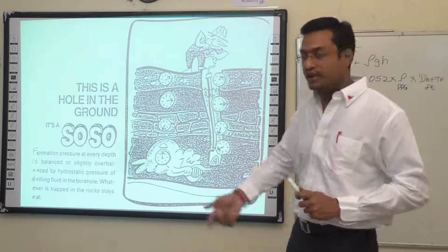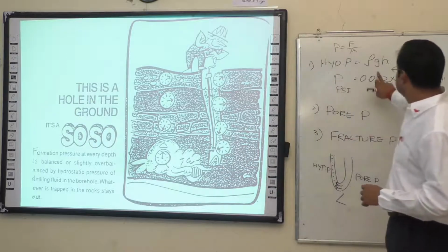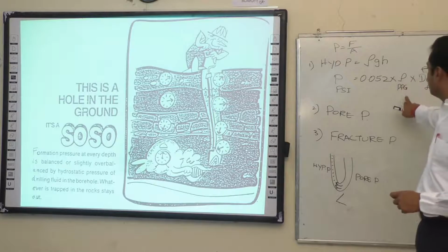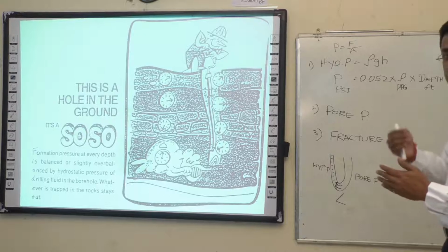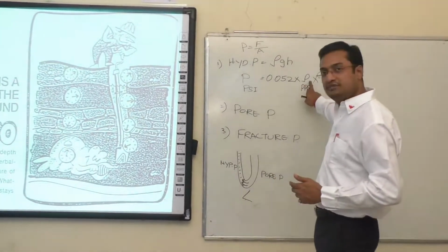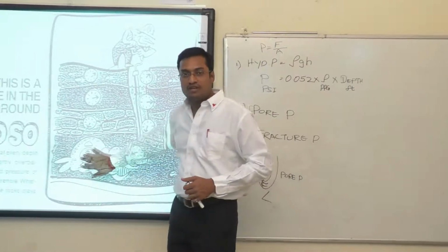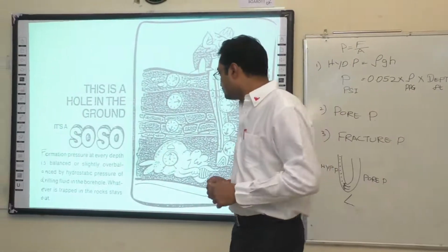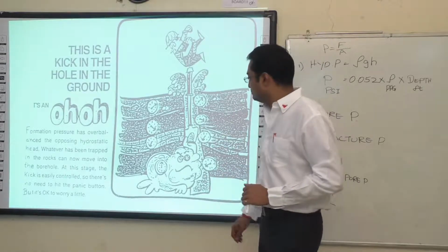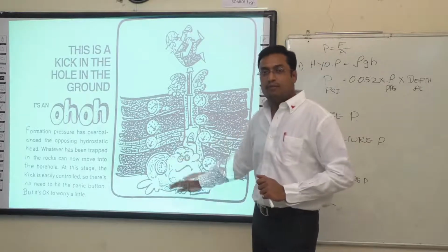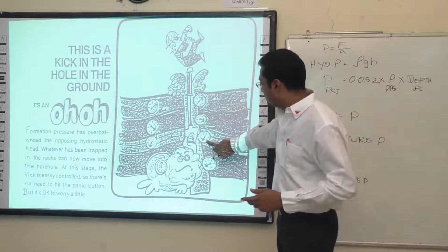So we circulate drilling fluid. So we have to decide on the right density. The density is given in ppg, pounds per gallon, and we have to formulate the density for a particular depth so that we always keep control of the pore pressure. Okay? So when we are drilling, with a balanced condition, no problem. But for any reason, because of any problems, if this pressure